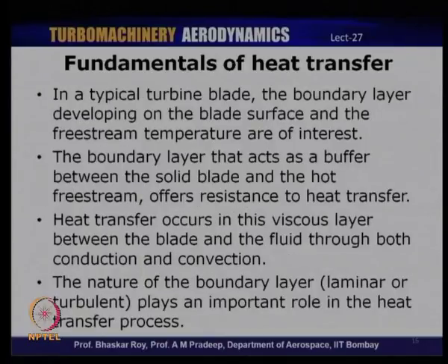Now, in a typical turbine blade, the boundary layer developing on the blade surface is also of significant interest, because the boundary layer sort of acts as a buffer between the solid blade and the hot free stream, and it offers resistance to heat transfer between the blade and the free stream.